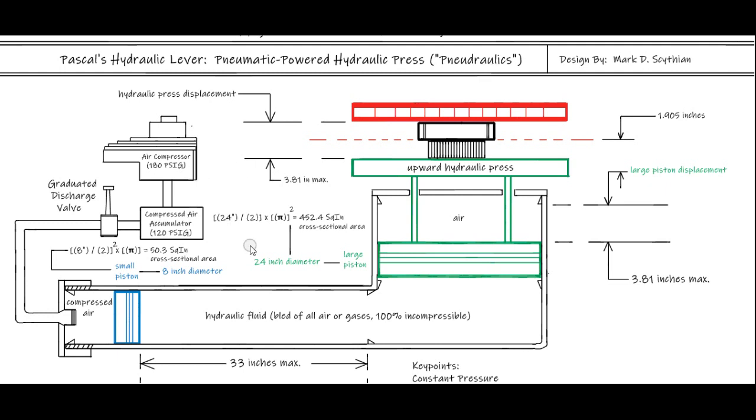So here, the function is to amplify force through the hydraulic lever, for which Pascal's law asserts that when a fluid, either a liquid or a gas, is transmitting pressure and then subsequent force, the pressure across the fluid medium, in this case incompressible liquid, known as hydraulic fluid, will remain constant throughout the incompressible liquid